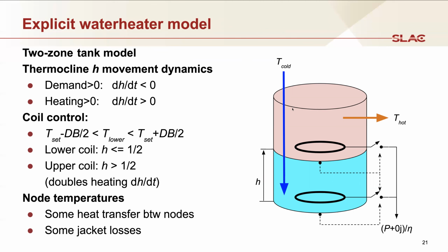Water heaters do not mix water when they bring water in to replace hot water that's been removed. The water is added to the bottom in a laminar flow so that the mixing is minimized, and then that cold water slug is heated up. This is done so that your hot water remains hot as long as possible as you draw water out. If it were fully mixed, your hot water would start cooling off right away, and that would not be as comfortable. You'd find your water temperature varying quite quickly.